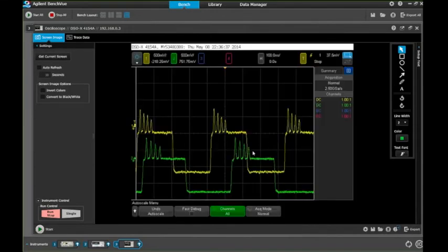All right, so we're a little bit overlapped now, but the DDS generator is at 4 points, which I didn't change at all, but I was able to simulate this DDS signal, my real-world signal, if you will, with my Trueform generator. So all I did was drag and drop it, change a couple settings to make the signals match, and now we have it. So you can change your frequency settings and amplitude settings as you wish on your real-world signal.